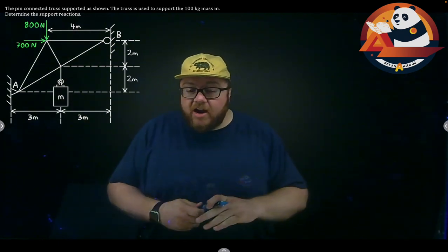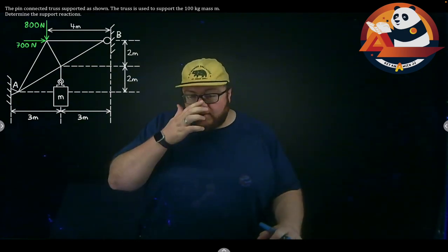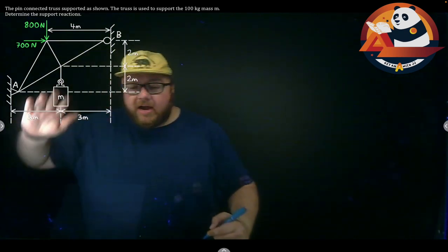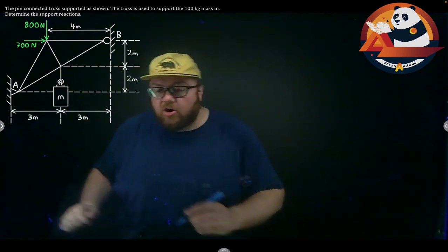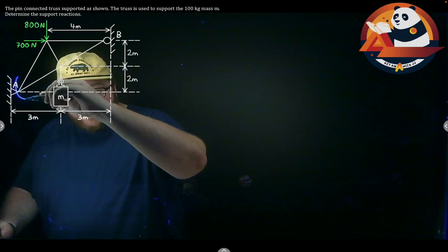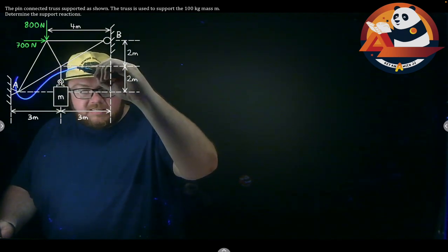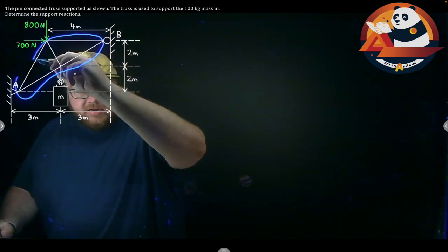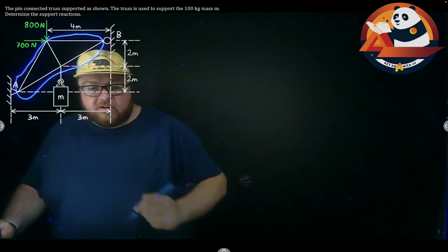So again, we're going to start out and tackle a free body diagram. We have to have a free body diagram for making equilibrium equations, so that should be our first step. For doing that, let's start by circling around our object, cutting it off of the wall that's holding it up, or the ground. Any weight that's hanging off of something, we'll snip that rope as well and go from there. So we'll cut the mass's cable, come up and around and cut through the roller, and then we can close out that circle.